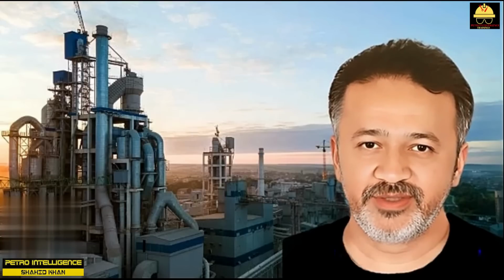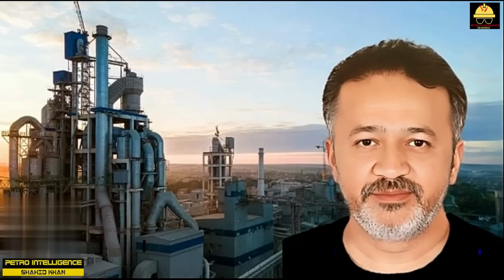He designed a new bundle, using the existing shell and nozzles, with new tube support baffles. He mostly eliminated the parallel component of shell side flow. The observed heat transfer coefficient improved to 80 BTU per hour per square feet per degree F. The increased thermosiphon driving force resulting from the larger reboiler duty and vapor generation rate offset the increased pressure drop caused by the new baffles. This kept the circulation rate through the shell constant.